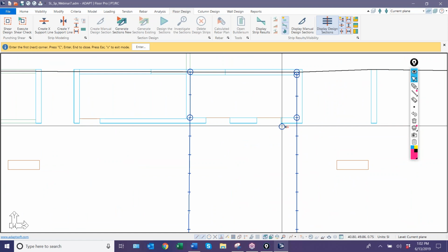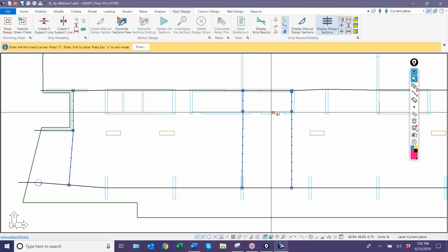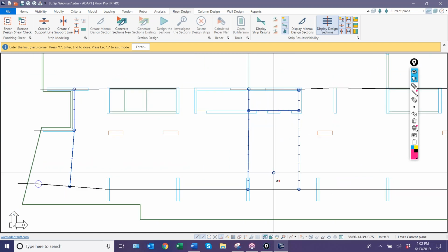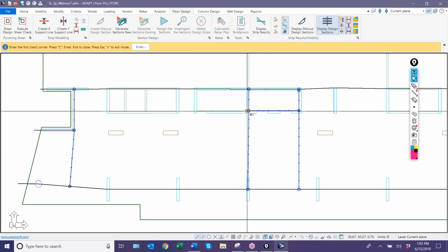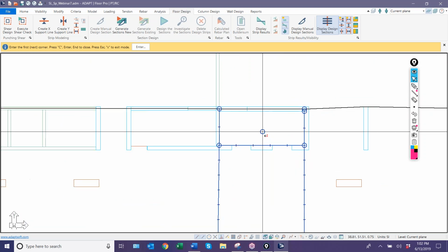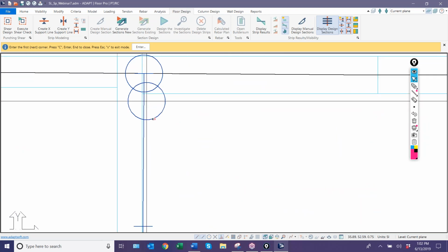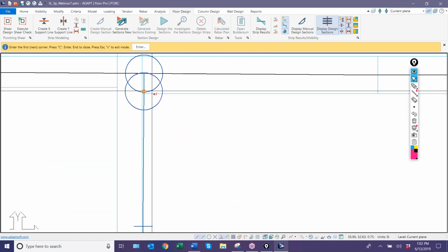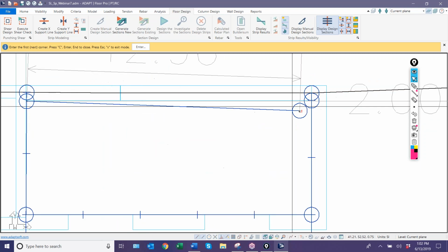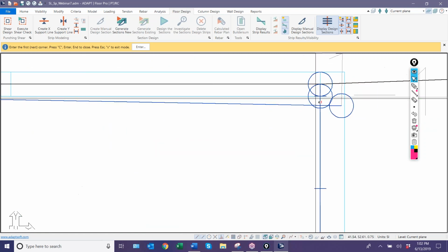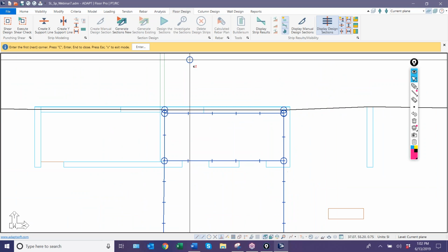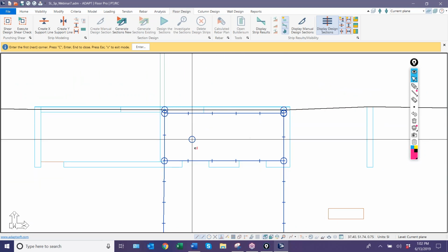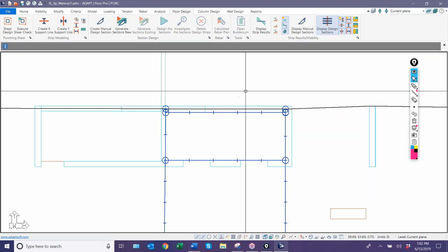Okay, and now I'm going to create a boundary. I'm going to say for this support line below, I want it to stop at this splitter that I'm adding. It can't cross into the opening now because there's a boundary there. And likewise on the opposite side, I could put another splitter, let's say from that support line over to the one on the opposite side. And this will stop at that boundary. Nothing will happen in this zone because there's no support line there.